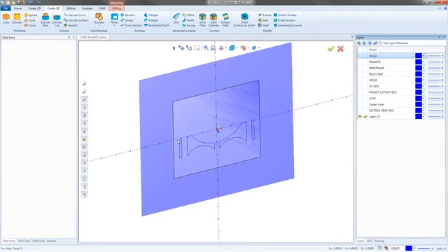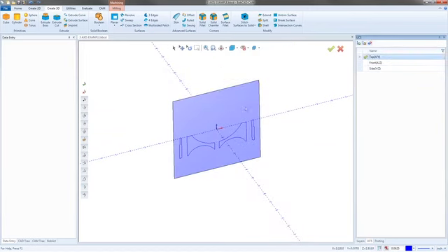If we turn off the solid, we're left with the same geometry. So it's whichever way you want to go about it. You can use the section view, or you can use the intersection curves. The problem with the intersection curves is you usually need to make extra geometry. I will say, though, I probably use intersection curves more than I use the section view option. I think I keep saying cross section. I mean section view, not cross section.